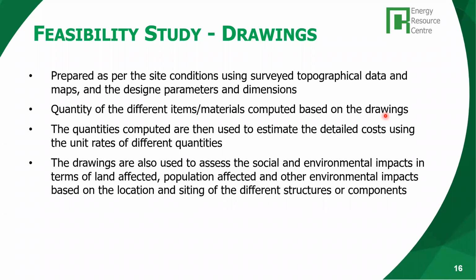This arch dam is designed to suit the site there. If it was a different location or a different river, a different topography, the dimensions, even the type of the dam, would be different. So one key word is the site condition for hydropower projects. We prepare a topographical map, and based on that map we locate these structures, and the drawings will show these structures and their dimensions.